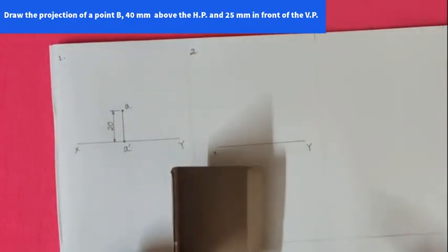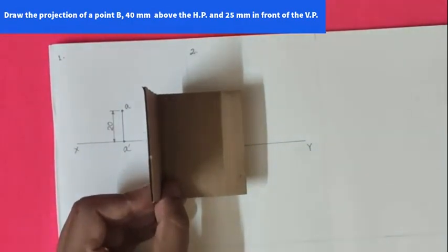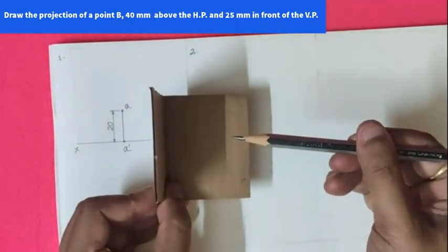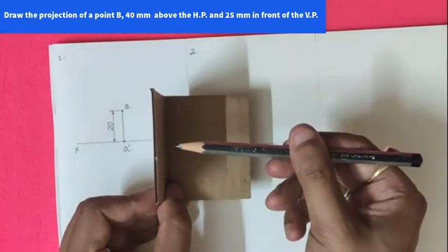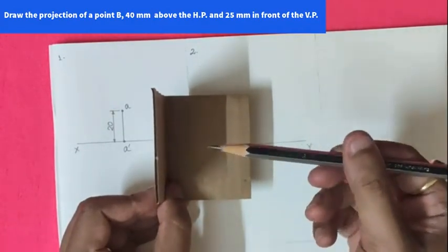Now, the point is 40 mm above the HP. So when we see from the front, this point will be projected in the vertical plane. This distance will be 40 mm above the HP.